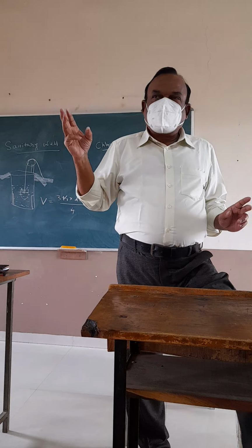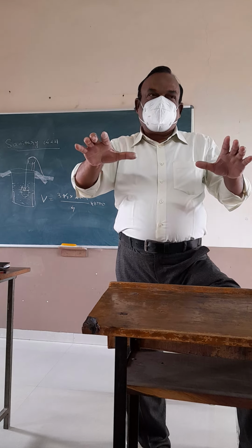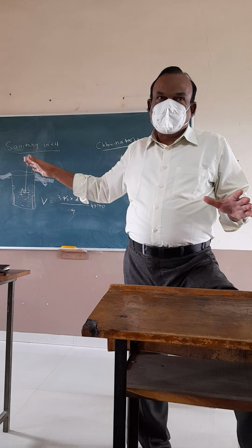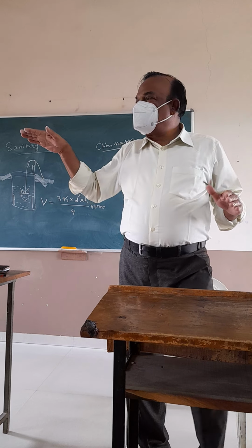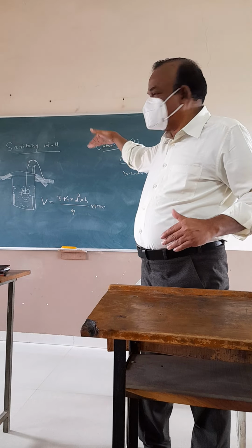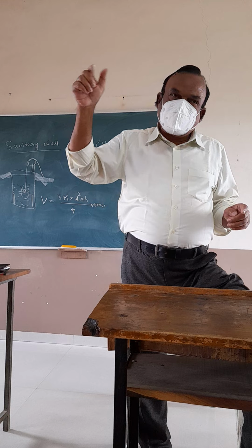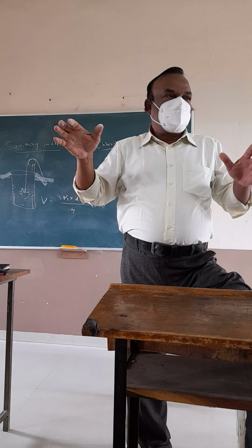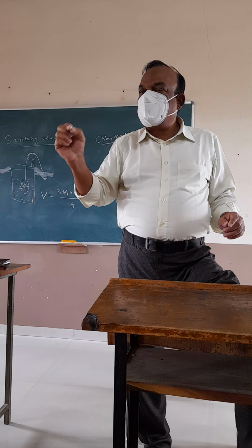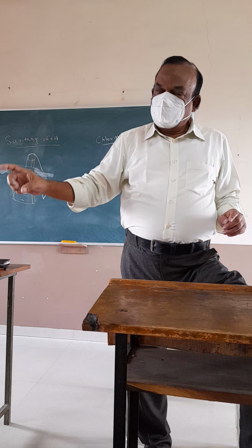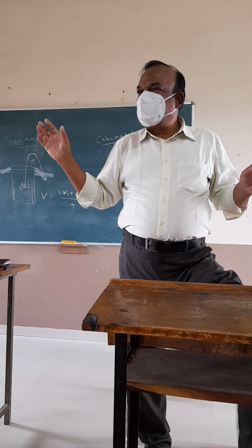Number 3, the platform of the well. The platform of the well has to be elevated and constructed with cement concrete, and there should be a slant so that whatever water is drawn from the well does not enter the well again. Rather, it should drain away from the well, to avoid contamination of the well by used water. If contamination occurs, the purpose of the sanitary well is lost.